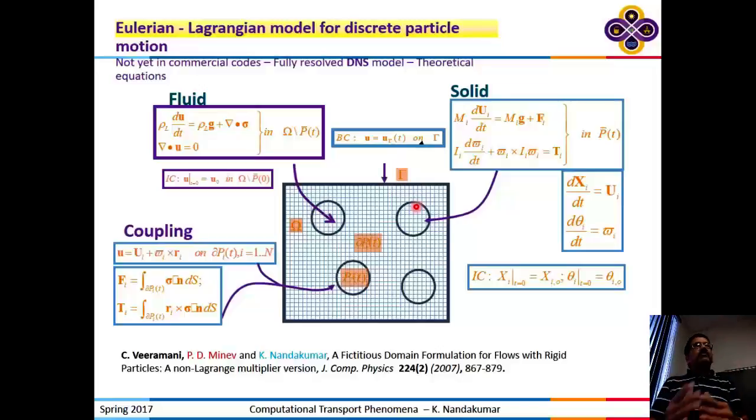Okay, whereas in the fluid, it can sustain a shear, and that is captured in this term. But in particles, you have gravity acting on the entire mass, or a force. This is the equivalent of the force field in molecular dynamics simulation for interacting spheres. But here, this force is calculated from the stresses acting on the surface. So in a fully resolved simulation, you will have velocity gradients of the fluid at every point. And so you can integrate that.